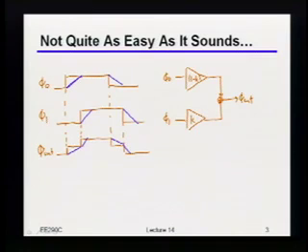Still not perfect, but that's a heck of a lot better. Now I've actually got some reasonably well-defined thing that kind of looks like a real clock waveform. So indeed what we're basically saying is we need to smoothen the edges out.